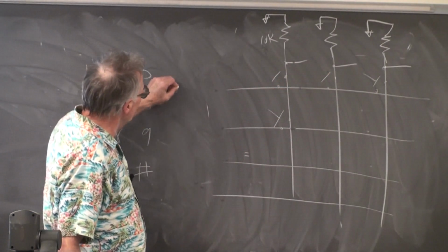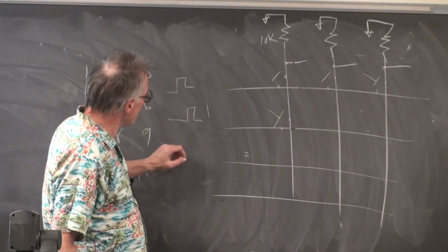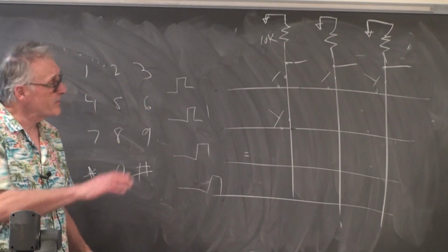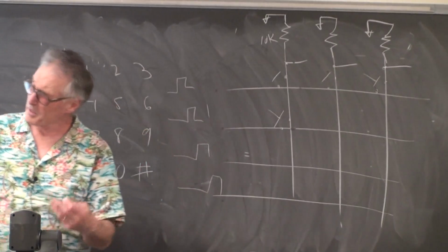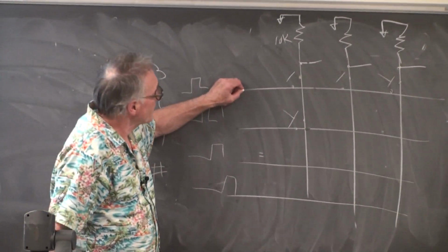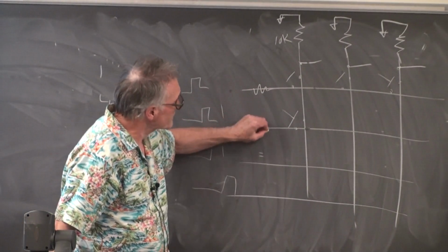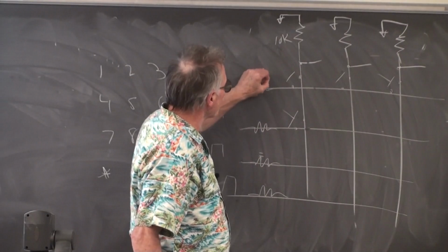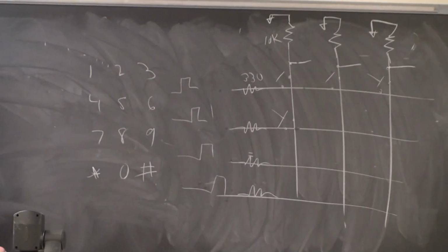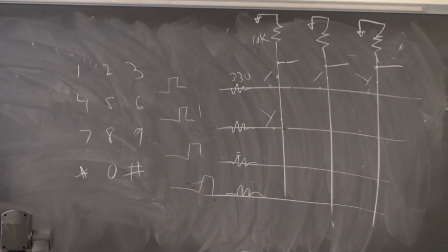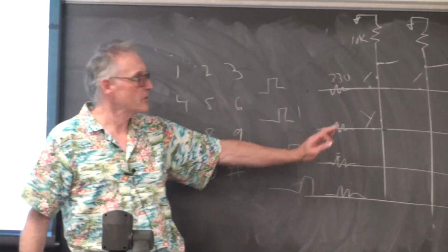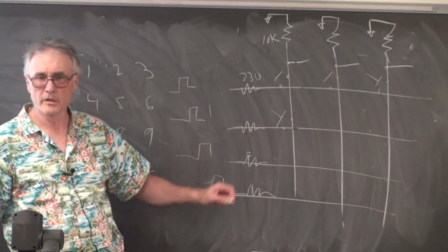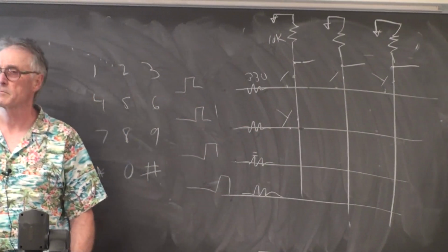So we're going to sequentially put a pulse here, then a pulse here, then a pulse here, then a pulse here. We're going to drive these all off of 1 port so we can manipulate them all simultaneously. And without fail, you must put resistors here, typically 330 ohms, more or less. And why is that? These are all going to be set to outputs. These are all going to be set to inputs. Why are these absolutely necessary in this case? This is not optional, it's necessary.